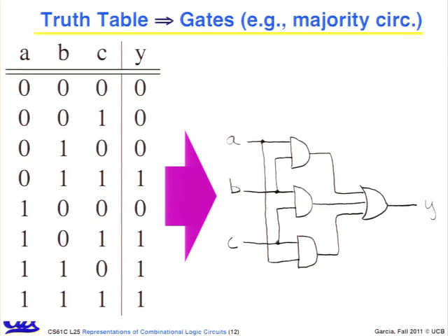Let's see. Okay, it's a 1 if, let's do the first one, B and C, then it's a 1. Okay, B and C, or A and C, and there's A and C, or A and B, and that's there. But there's also, what happens? Don't you need another one? Don't you need A and B and C? Don't you need that? Well, it turns out you don't need that term because you've covered all the cases already.